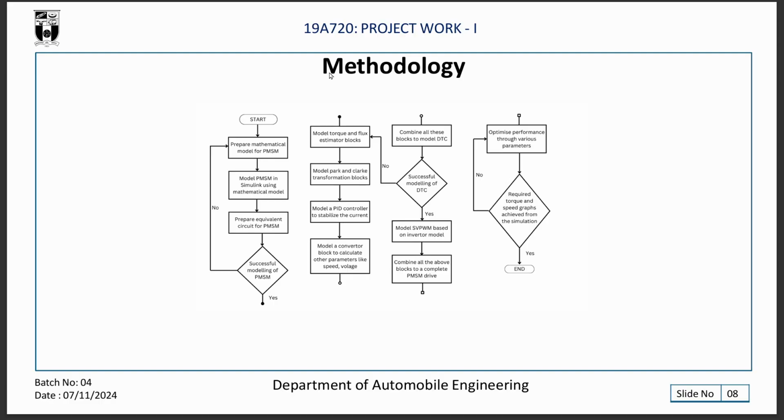So the methodology that we have incorporated during the development of this project is, first we prepare a mathematical model for the PMSM motor, then the model of PMSM in Simulink using the mathematical model, then an equivalent circuit is designed for the PMSM motor. After the successful modeling of PMSM, we created a model of torque and flux estimator blocks, and we have also made Park and Clarke transformation blocks, which convert the voltage into vector forms.